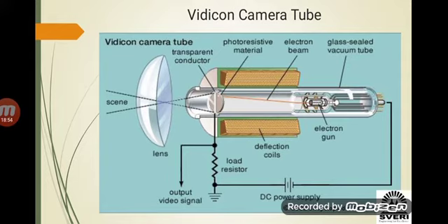So in the photoresist material, the varying intensity is converted or deposited in the form of varying resistance. Now the aim is to capture those resistance values, and from that derive our output video signal, which is located here at the bottom side, at the leftmost side.